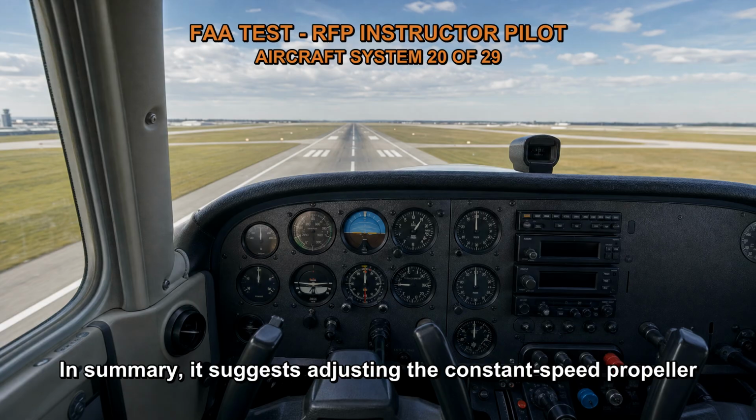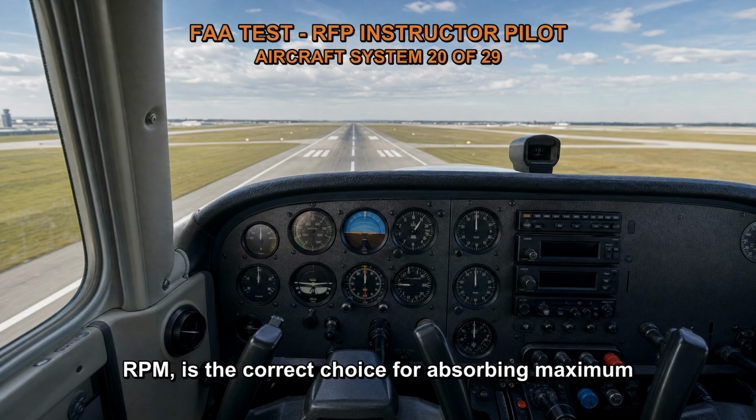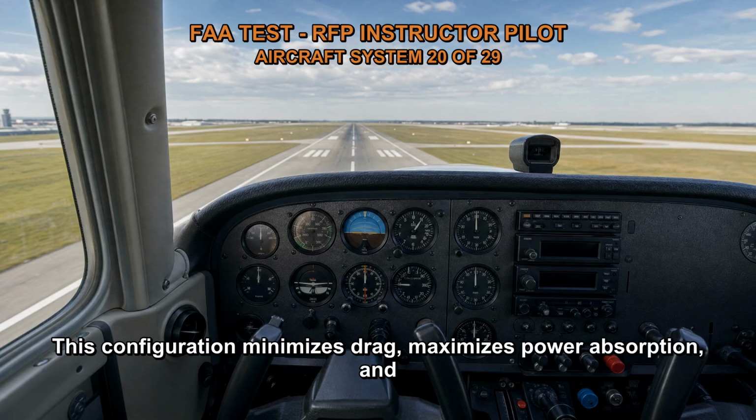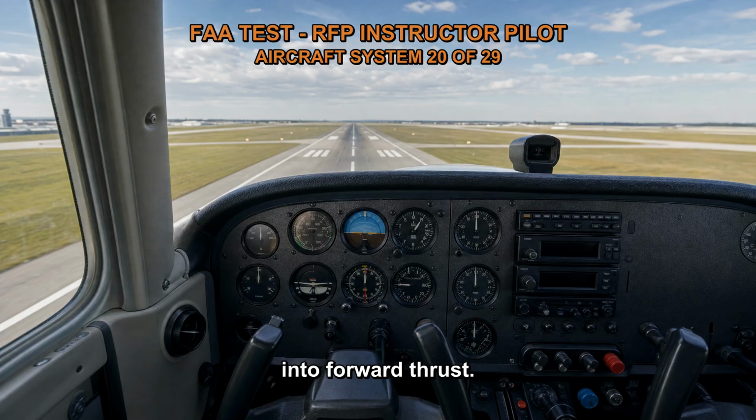In summary, adjusting the constant speed propeller to a small angle of attack and high RPM is the correct choice for absorbing maximum engine power and developing maximum thrust. This configuration minimizes drag, maximizes power absorption, and optimizes the propeller's ability to convert engine power into forward thrust.